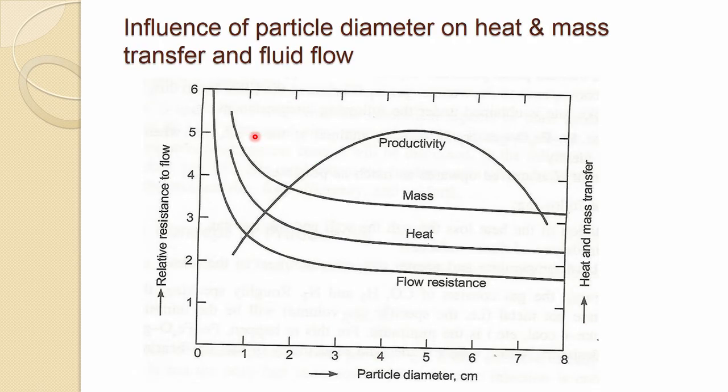And when we talked about the size and other things, you can also see another thing from this. As your size decreases, you can see more heat transfer and mass transfer takes place, especially below 10 millimeter. It increases in a sort of exponential way, because the surface area is very high when the size is less than 10 millimeter.